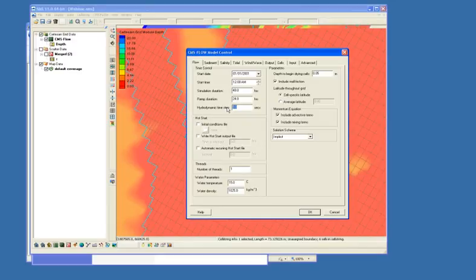Sometimes you can get by with a little bit more. So we normally take that value, whatever is showing, and halve it. Just for right now, I'm going to put in 1 second, assuming we're going to use an explicit solution, and then I'll cover a little bit more about the difference between implicit and explicit in a few minutes.